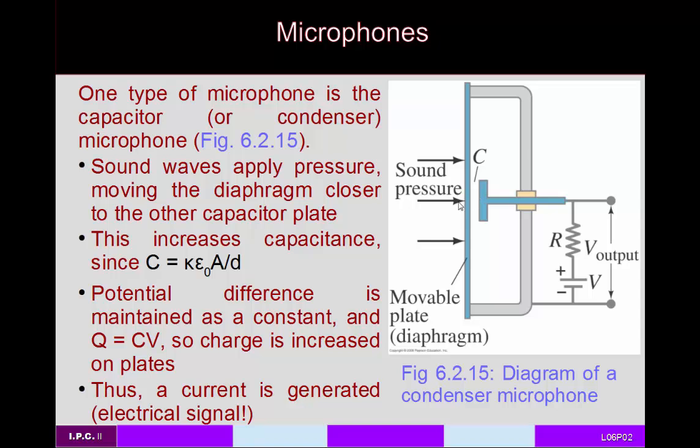Your electrical signal is the current generated from the vibration of this thing and the change of charge on the two plates. And now that you have your electrical signal, now you've built a microphone. You speak in through, you're speaking out here, that sound waves, it's vibrating this plate that generates a signal, which then is interpreted as, for example, a frequency of sound. And then how large the vibration is determines how loud the sound is. This is going to determine the maximum current and minimum current.